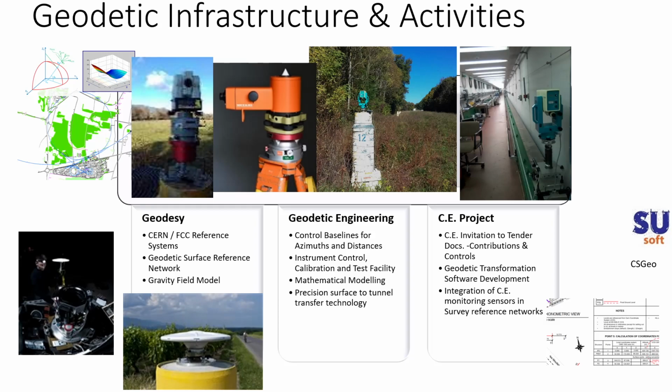Gravity field model is necessary for correct recalculation of geodetic heights gathered by GPS receivers to normal heights. So we just need to know the local geoid surface and the difference between ellipsoid and geoid in the particular area.